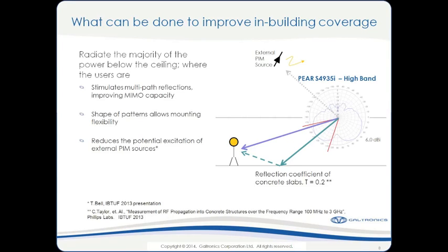So I need to be able to control my sector boundary and try to avoid these hard handoff scenarios when I get in gray areas between DAS and small cells, or when I'm outside, I don't want to be covering areas where I might be interfering with the existing macro network. So control of the radiation into a confined and defined space.